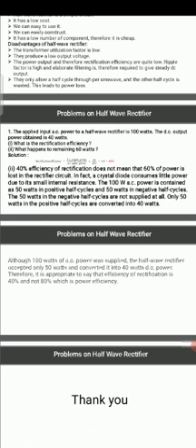The rectification efficiency is only 40% or 40.6%, because we use only the positive half cycle. All negative half cycles are blocked in a half wave rectifier.